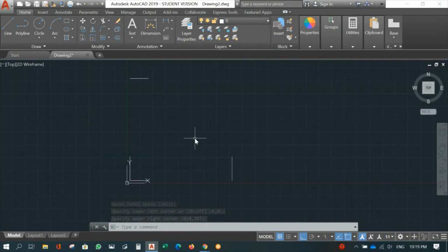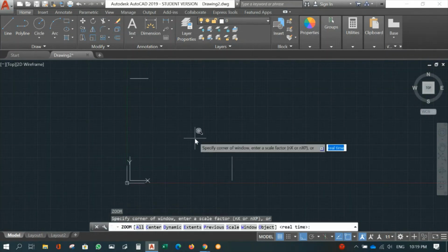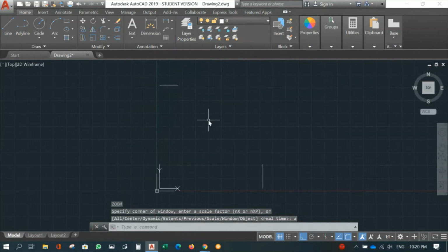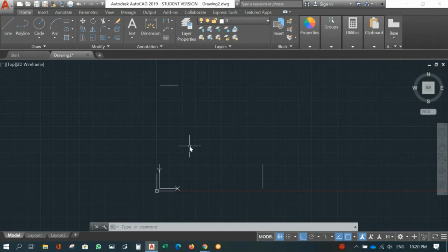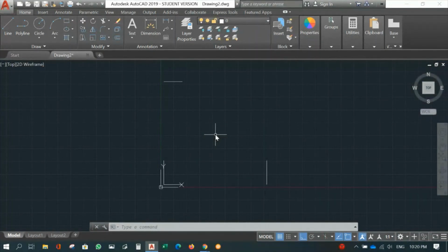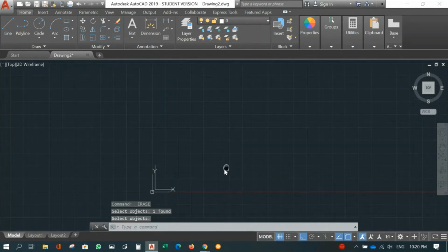It means that whenever we do zoom all, Z, spacebar, A, we're brought to this size. You will not lose your lines if, say, your view goes somewhere else. When you press zoom all, it comes back to where you saved your limit just now. When you have done this, you can delete all the lines inside here. Okay, done.